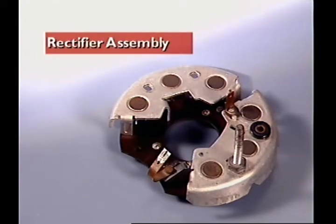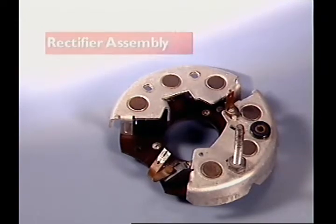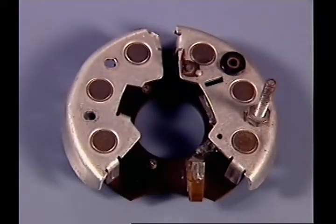This section examines the rectifier assembly. The diodes for rectification are mounted on heat sinks in packs of 3. One heat sink has 3 positive diodes and the other has 3 negative diodes.